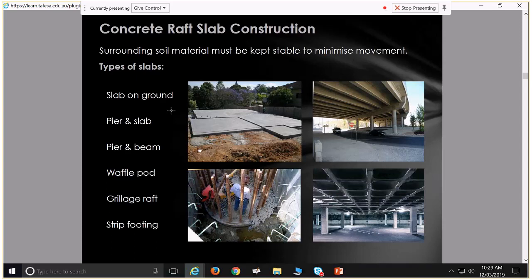So to make things more cost-effective, you remove material from one portion and then add it to create depth of profile, rather than just using it straight through. But let's say we had a cubic meter of concrete. We have a defined given amount of concrete that we have to work with. If we made that cubic meter of concrete 200 mils thick, we'll get 5 square meters out of it, and we'll get a certain strength out of it. Whereas if we decided to make it 100 mil thick in sections, but 300 mils deeper for our beams, that same cubic meter of concrete, we can make a larger footprint from it, but be the same strength.